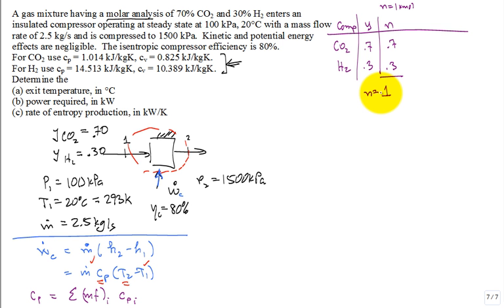But now that in my mind I know that I started with 1 kilomole of the mixture, and I'll have 0.7 and 0.3 kilomoles of this component and that component, if I knew the molar mass of that component, what is the molar mass of CO2? 44.01. I look it up in the table. It's around 44 from memory. Carbon, 12. Each of the oxygen, 16. So 2 times 16, 32. Add 12, 44, with some change from the table. Okay?